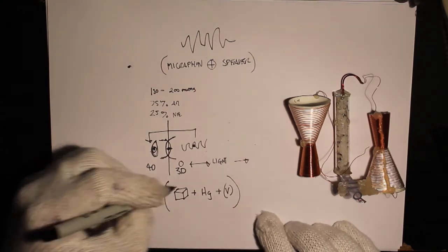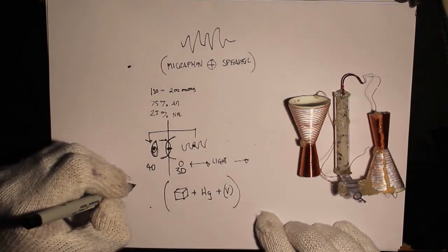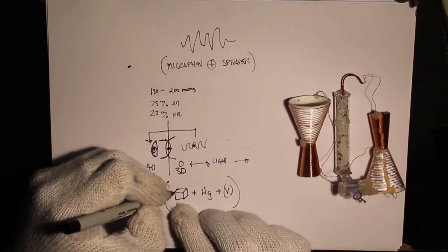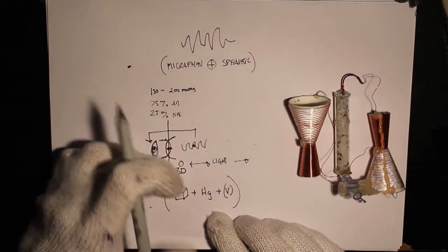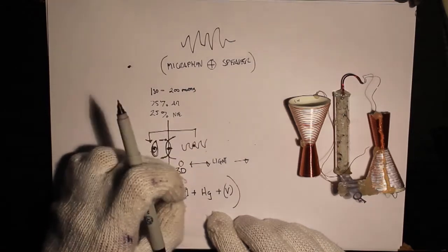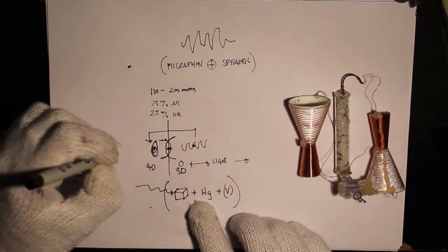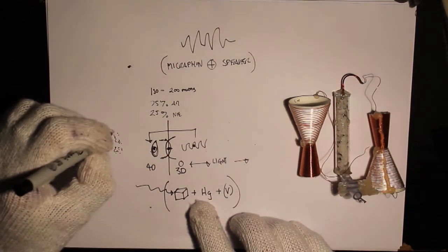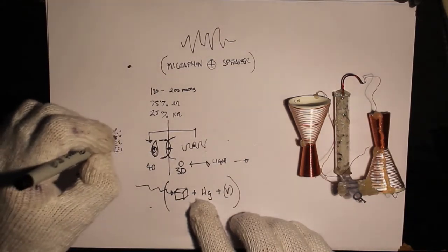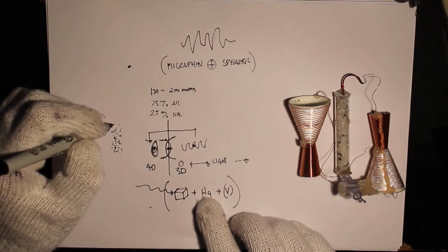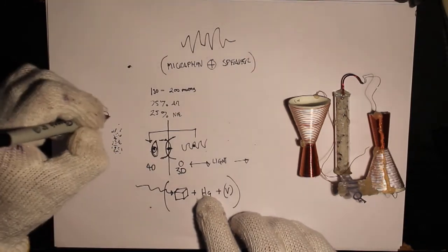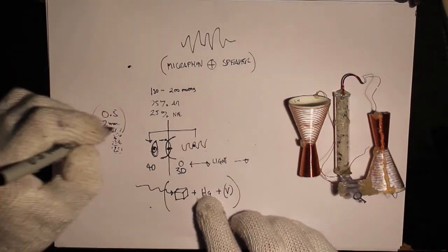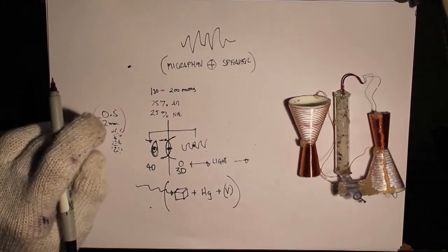The pressure in the other dimension coming in hits the salt crystal and distorts it, creating a piezoelectric charge. As you'll notice, there are thousands of little crystals in that tube, and they have an optimum diameter of about 2 mils, between 0.5 and 2 mils, where they most efficiently work for the spectrum required.